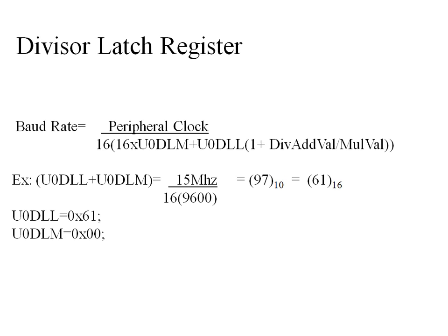Basically, we divide the processor clock because the processor is much faster compared to the peripherals, and also we want to reduce the power consumption. For that reason, we divide the incoming clock using the VPB divider. That's the reason we got 15 megahertz here, which is the peripheral clock. So all the peripherals receive only 15 megahertz.